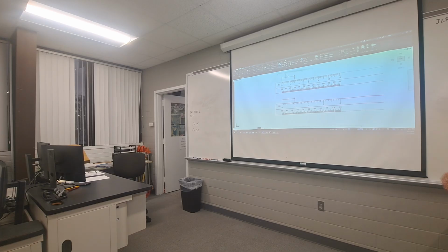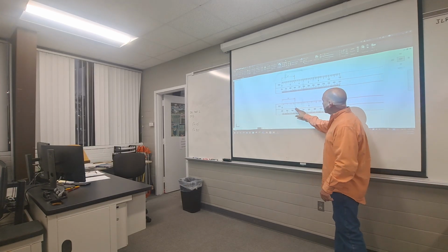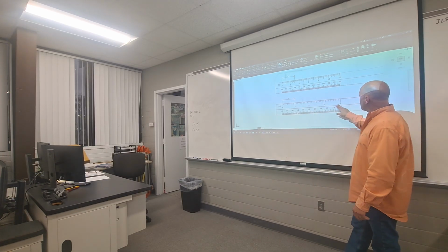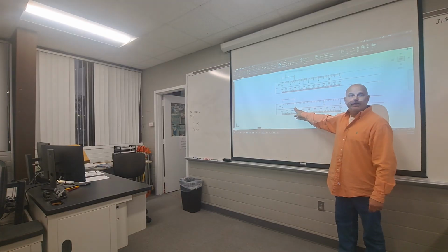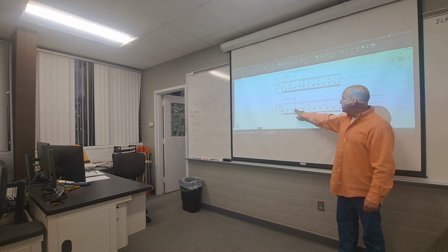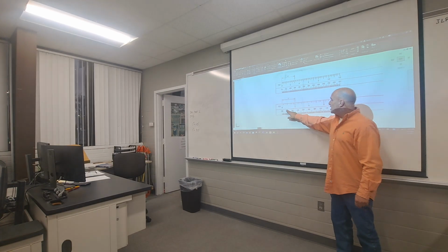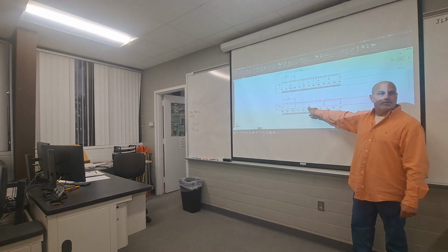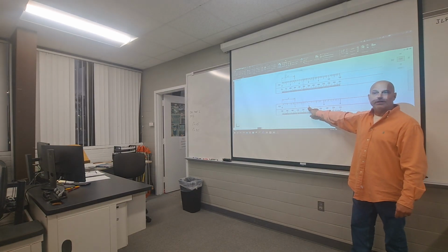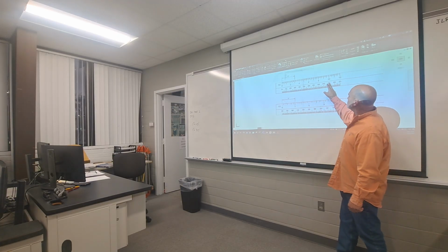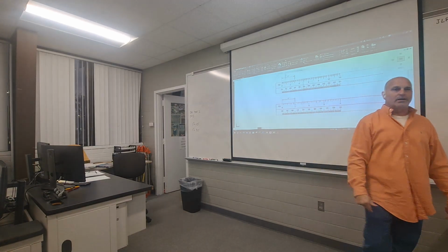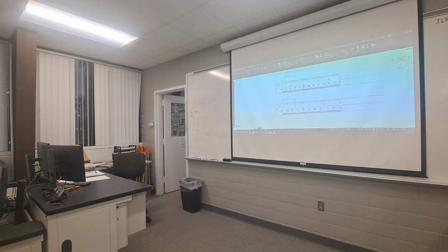So each one of these, when you look at these numbers, understand that each one of those should have a 0 behind it. That is not 1 foot from there to there, as the note says. That is 10 feet. That is not 2 feet from there to there. It's 20 feet. So you just envision, no matter what blade you're looking at, Mr. P, these numbers are pretty high. I don't care, put a 0 behind it. So that's the first thing I need you to learn about that scale.